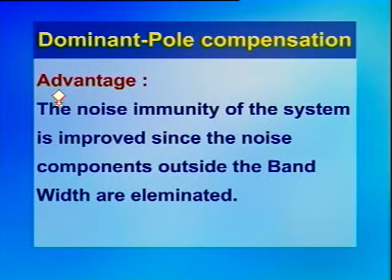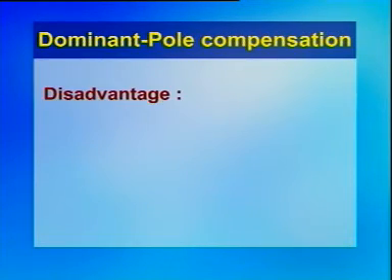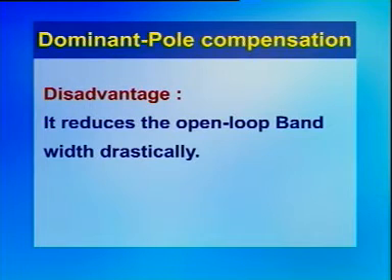The advantage of this particular compensating technique is that the noise immunity of the system is improved since the noise components outside the bandwidth are eliminated. It also has a disadvantage. It reduces the open loop bandwidth drastically.